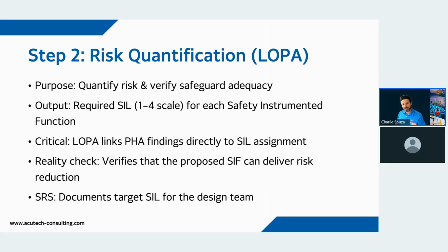And again, if the LOPA says you must have a certain risk reduction factor, it's your responsibility at the end of the day, as a PSM, as a process safety manager, to verify that the risk reduction factor is indeed achieved in the field and has been kept in the field over the years with maintenance and testing, and so on and so forth.